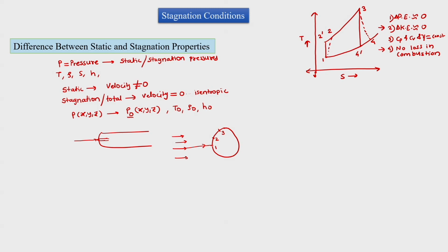So the pressure measured at point 1 is a stagnation pressure, but at point 2 flow will not be stagnant, since the normal direction is this, and velocity is not in the direction of the local normal. So there is a component of velocity which is not letting it go to 0, and that is why velocity is not 0 at point 2 and also at point 3. The pressure measured at points 2 and 3 is a static pressure.